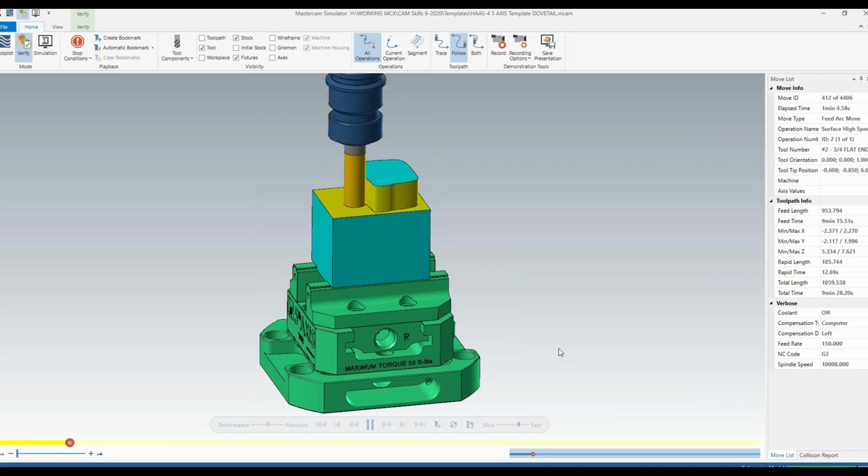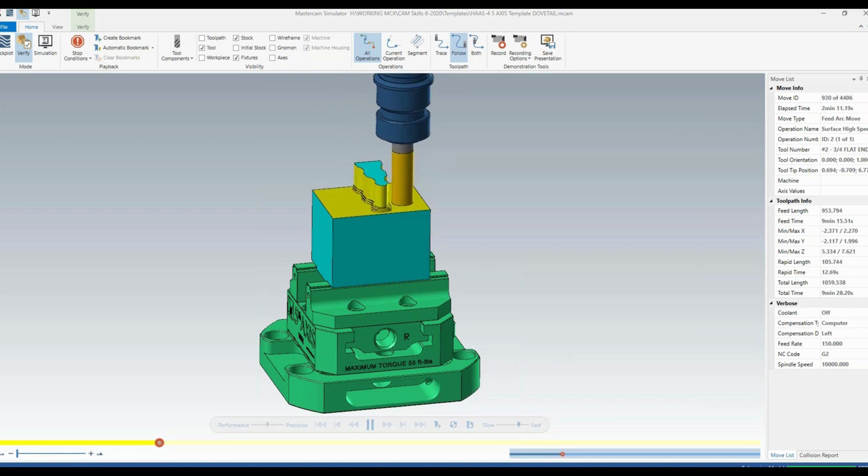So if you've got a good fixture or a fixture you tend to use a lot, or a machine that's sort of your prep machine where you do quick turnarounds, try to build that world up as much as possible as a template. So you can just drop parts into it all day long and just program rather than worry about the setup. All of those things: tool data, taking the time to fill that out properly, taking advantage of the ability to auto-populate, exporting the good toolpaths and remembering to import them when you get the opportunity to use them again.